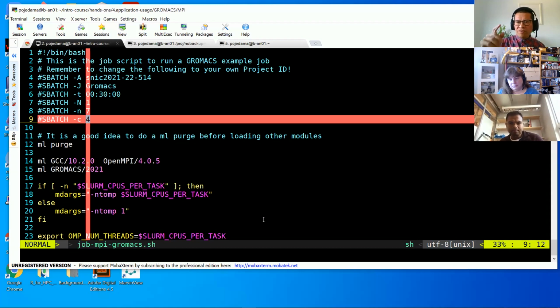The number of MPIs times the number of threads should be a multiple of 28 if you are using multiple nodes. In the present case, because we have only one node, this product should be 28. You can use any combination, for instance, 3 MPIs and 8 OpenMP, but that would not be very efficient, because then you will be using 24 cores, right?